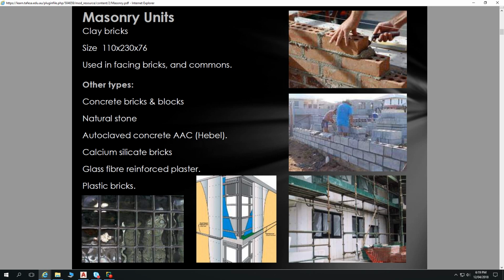So actually, while we're looking at the Mount Gambier limestone, that's a sawn section, and you stick those sections onto a solid wall to give that stone look. But here, this is part of a floor tile. It's not a good example, but a lot of you would have seen the stone veneer that you can buy in panels. It looks like stacked stone. There's all just little bits of stone stuck onto something which gets stuck onto the wall. So that's typically our use of stone within buildings.